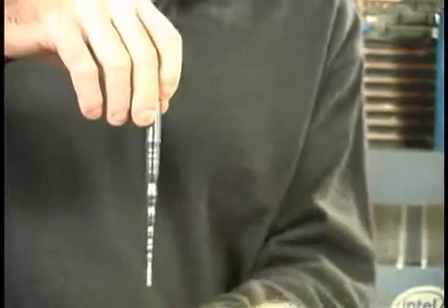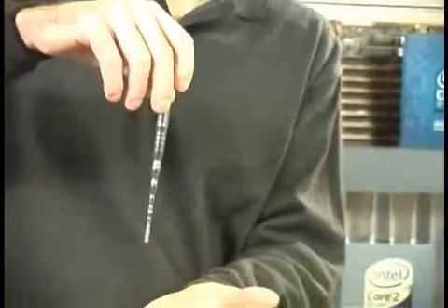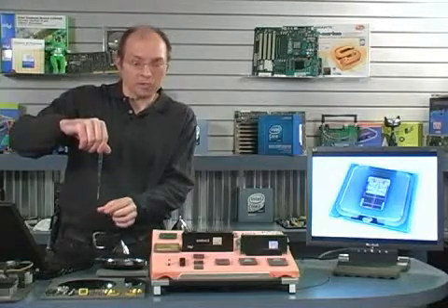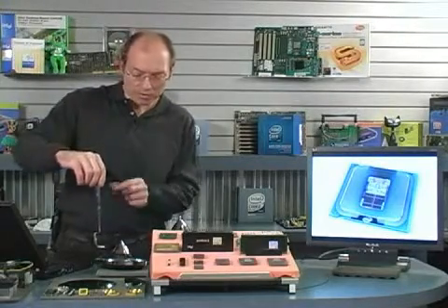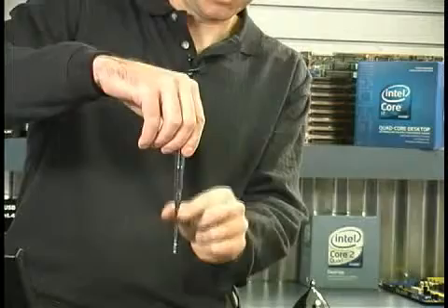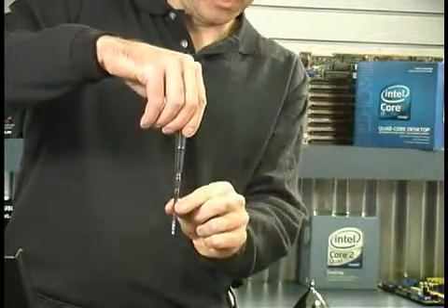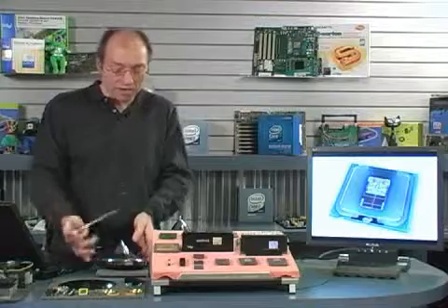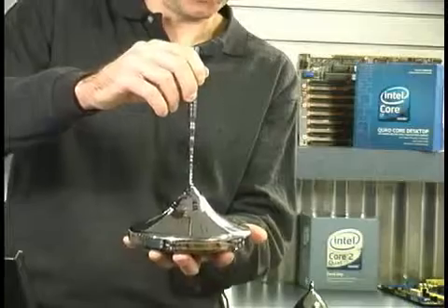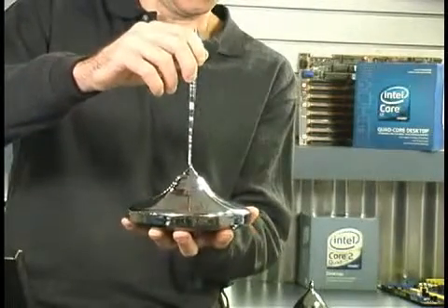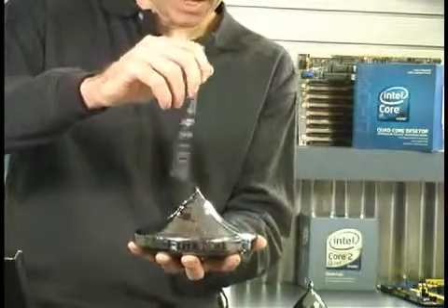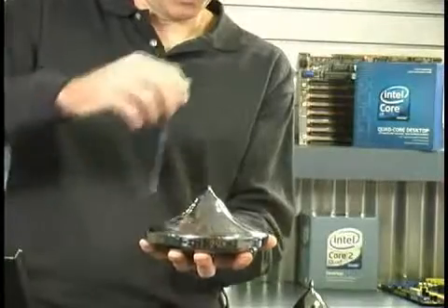Now, if you imagine this vat of molten material, it's kind of like melted glass. It's sort of thick and taffy-like. And as the crystal begins to pull out, some of the material sticks to it and begins to harden. So this seed crystal pulls out of the vat, and you can see a bunch of material sticking to it. They pull at first rapidly until we have a very thin stem forming, and then finally more slowly until a wider and wider crystal begins to emerge from the vat. This is an example of a pure silicon crystal that I have here that was grown in one of these vats. As you can see, the shoulder of the crystal gets wider and wider as it is pulled out.